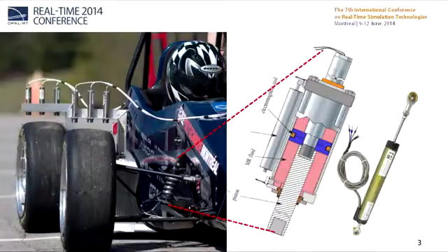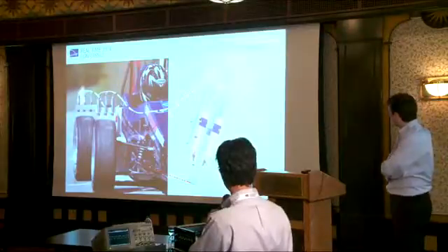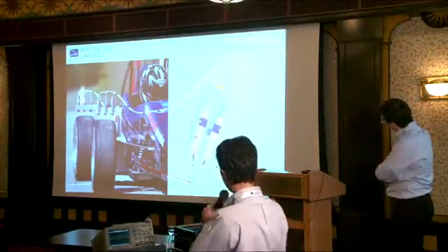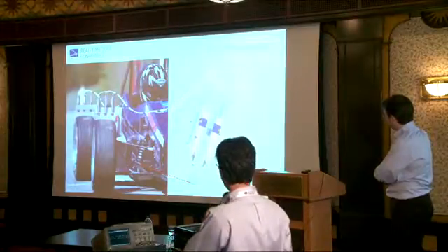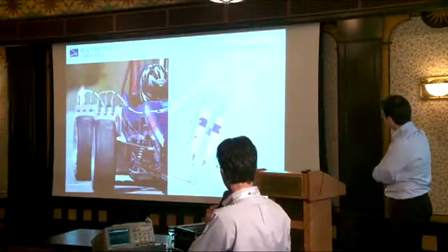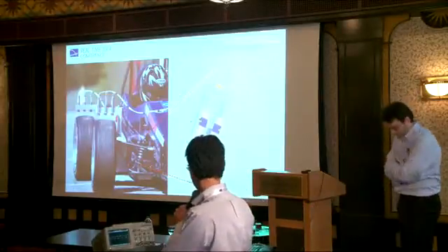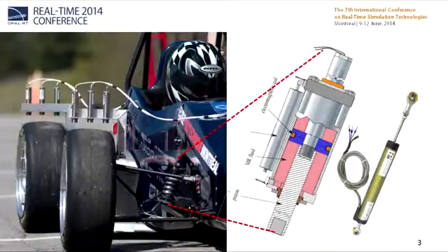So you have a car that is on the track, and you have a real-time controller, which can be an embedded PC, that will run a real-time closed-loop control algorithm that will adjust the suspension while the car is on the track. That was something real from the École Polytechnique of Montreal Formula ACE project. In order to control the damper, we have sensors, and those sensors, for example, are a simple linear variable resistor. So we measure the position of the wheel.